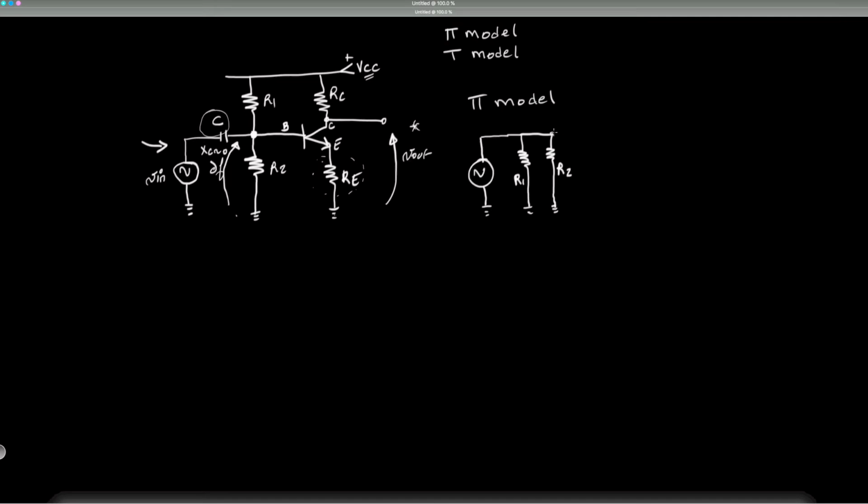And now, remember, this is still the base. But we have a resistance from base to emitter, but for the pi model, it is specifically expressed. And let me just put the emitter here now, and I will handle this in a minute. So what happens from the emitter to ground? Well, we have big RE. So this would be big RE, the same as this one.